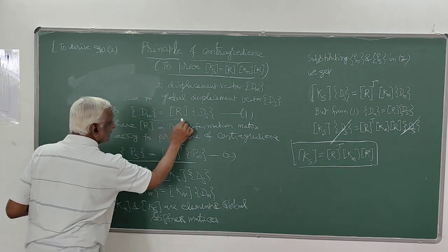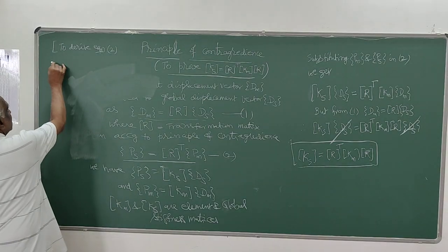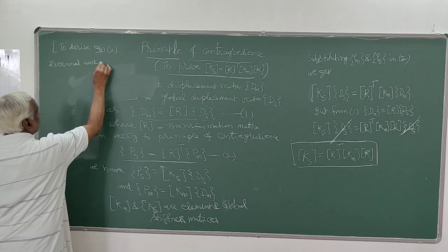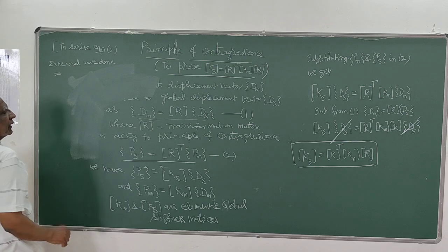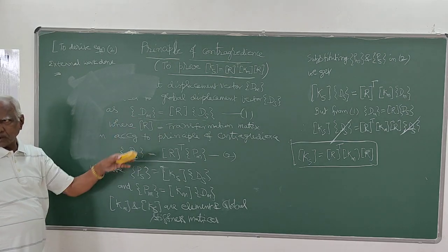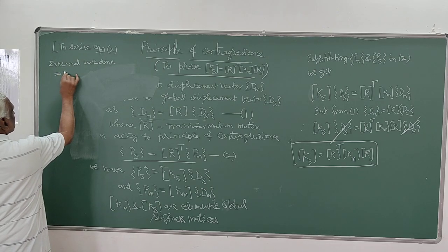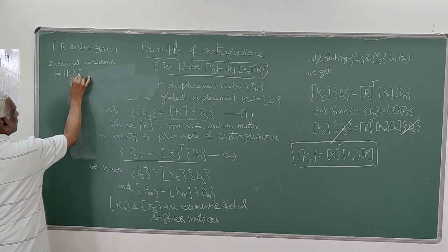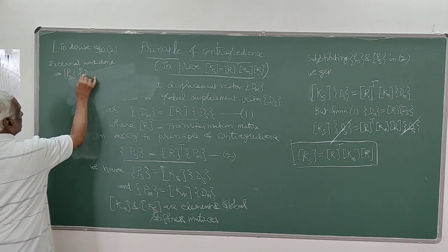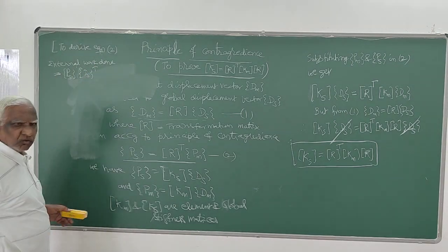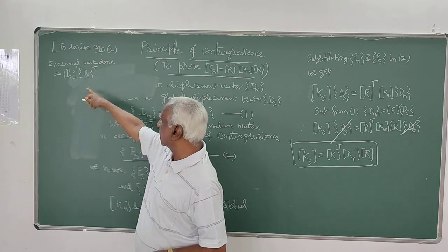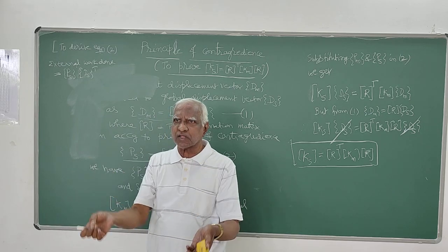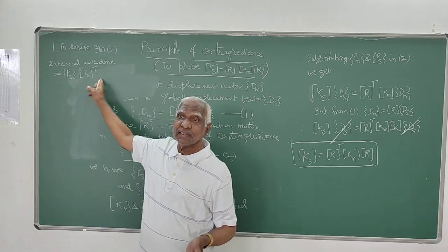So, you have this relationship, this is known. Then the external work done by the system of forces in local and global directions is equal to ds into dst. That's the external work done. Force into displacement. Global direction force. The forces acting in global direction are known. Corresponding displacement also you can measure. So you can find out the external work done.